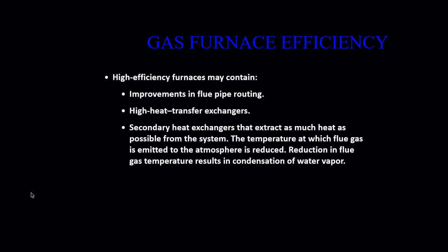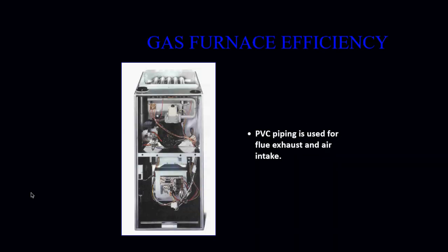Reduction of that flue gas temperature results in condensation of water vapor, hence the term a condensing warm air furnace. It is that condensation of water that we are generating by lowering the flue gas temperature before it exits the furnace that gives that furnace the efficiency that we are looking for.